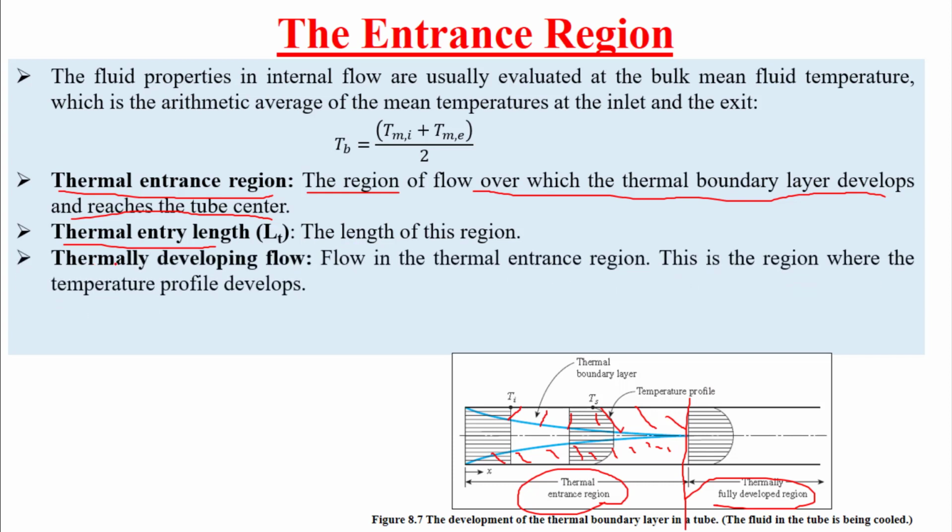The thermally developing flow is the flow in the thermal entrance region, this region where the temperature profile develops. So either we call it thermal entrance region, or we call it thermal developing flow.